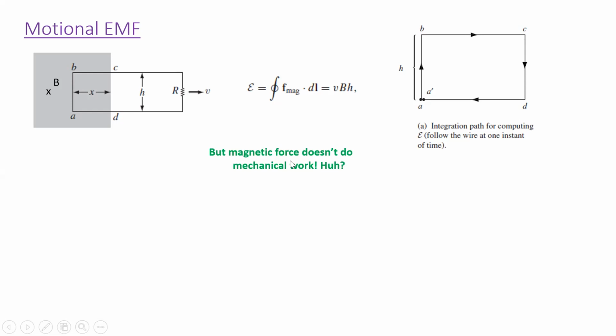And the answer to this is that as the current flows, the induced current flows upwards, it's going to experience another force because it's flowing upwards, and the magnetic field here is into the screen. And if you use your right-hand rule now to figure out which direction the force will be on it, it will be to the left.